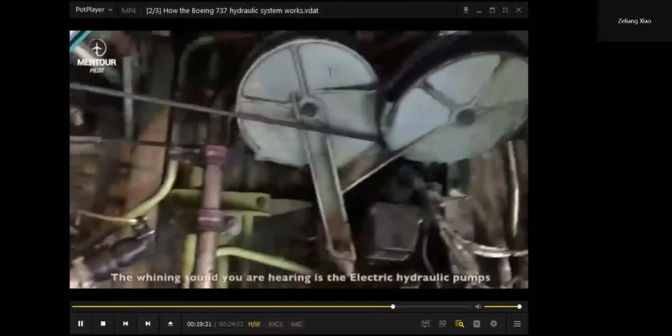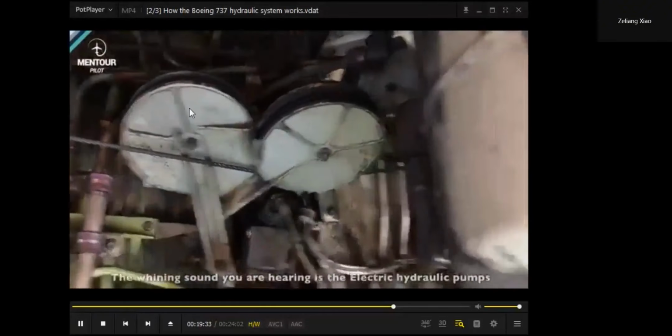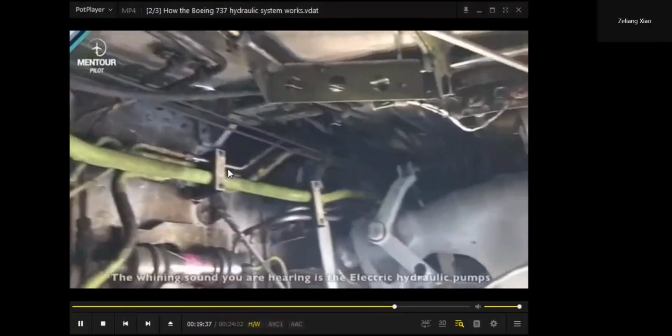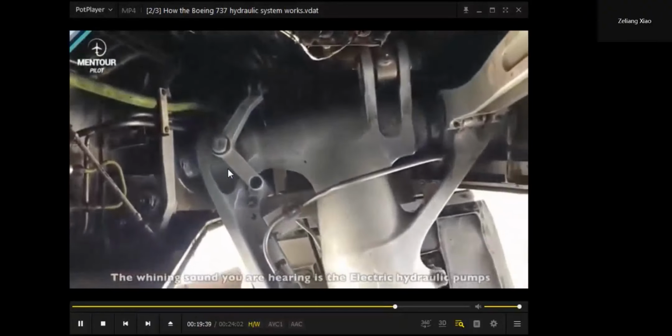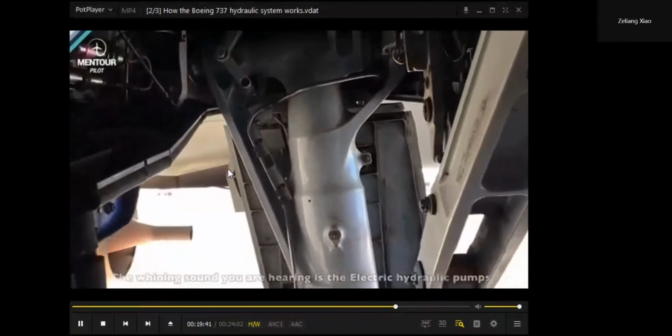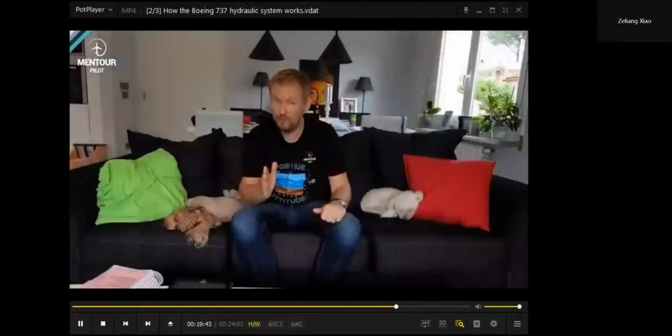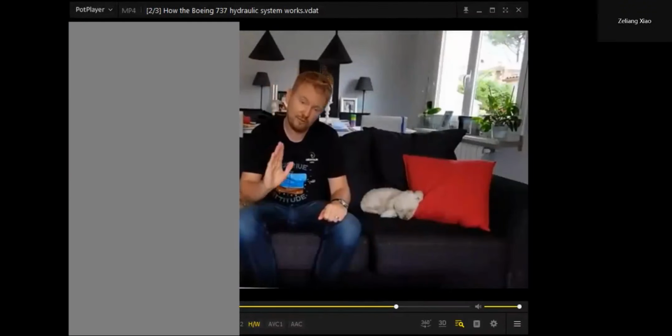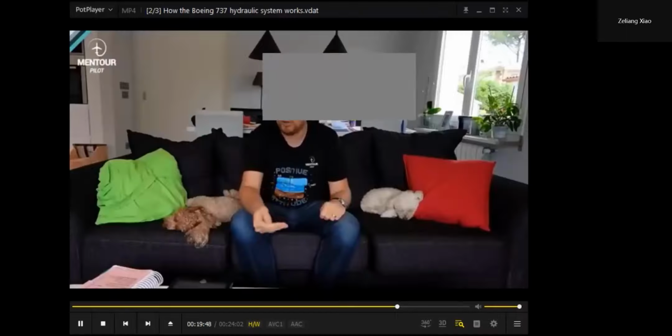The 737 is one of the only aircraft of this size left that actually has physical wires connected out to all of the flight controls. So if you lose system A and B, the rudder will still have some hydraulic help from the standby system. You will still have a standby yaw damper that will work, but ailerons, elevator, that's all by muscle power.